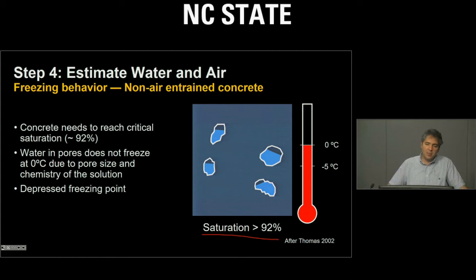And why that is important is because when ice forms inside the concrete, ice will start to expand. And when ice starts to expand, it will start to produce basically tensile stresses inside our concrete.